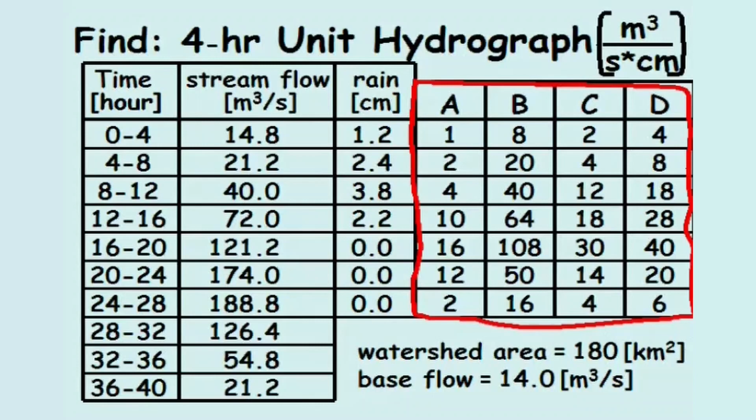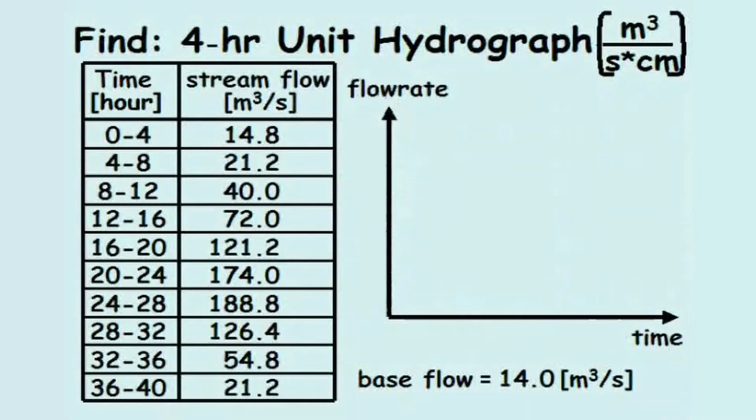Possible answers A, B, C, and D are shown on the right in units of meters cubed per second per centimeter of excess rainfall. Before developing the hydrograph, we'll first need to account for the base flow.